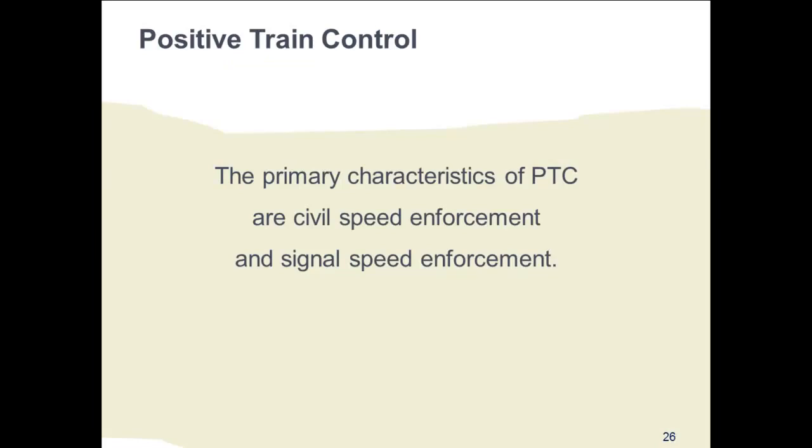Dick, we've talked a lot about the fail-safe principle and how it's manifested in railroad electrical, braking, signal, and communication systems. Given all this, why have we had the number of accidents recently? Well, despite the fail-safe equipment system, trained personnel can still exceed speed limits. They can advance through red signals at interlockings, as opposed to stopping, and they can fail to stop and proceed at restricted speed at an ABS red signal.